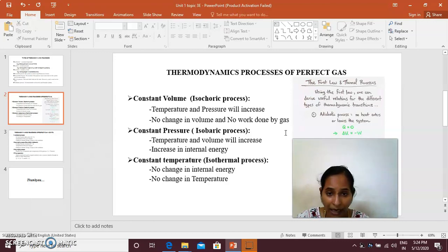Here, the relations between the state parameters such as pressure, temperature and volume are studied. The calculation of the change in internal energy, the evaluation of work and heat transferred, and the change in enthalpy are very important calculations, since they are the final output of the processes. What we want from the process is to have work done.